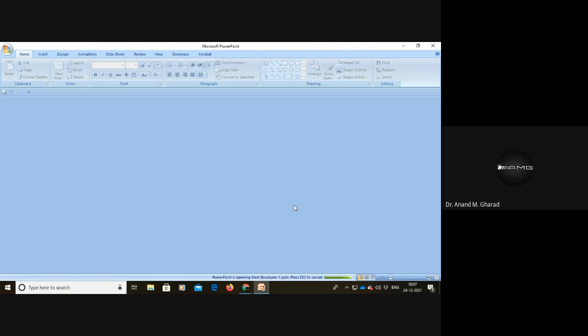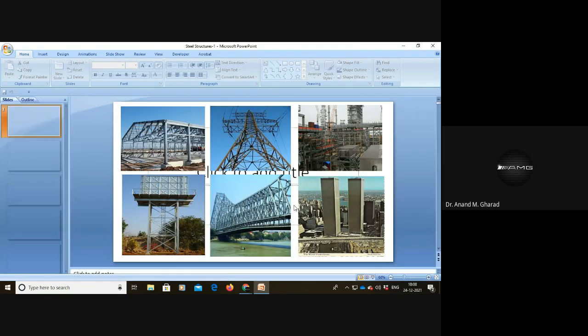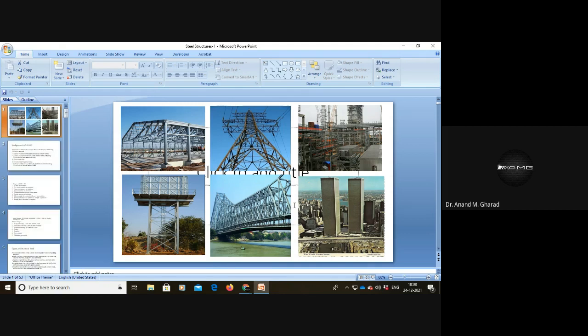And we have seen the difference between analysis and design. Analysis is related to the application of load on a given structure, and with the help of this application of load, you are supposed to find out certain values that will be essential in your design. Broadly, the output result of analysis is nothing but bending moment and shear force values. With the help of these values, you are supposed to design various components.